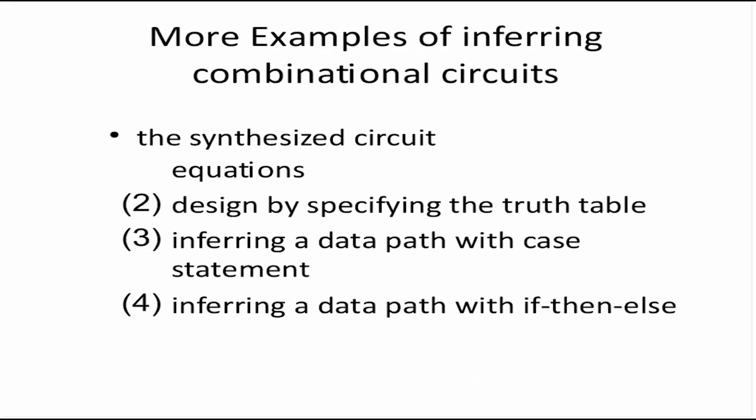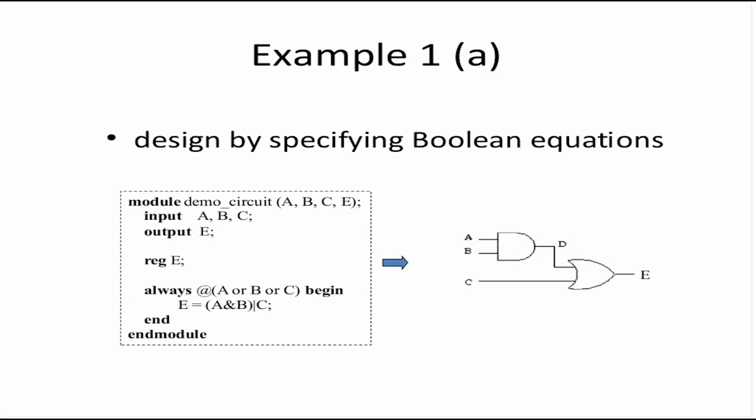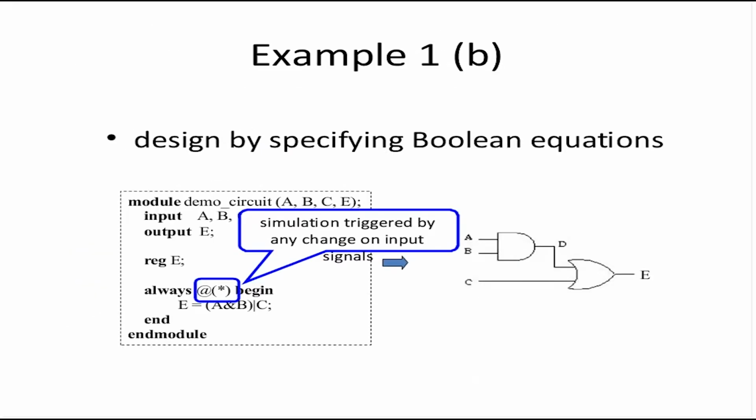That is why a very good practice is to use always @(*). It tells that simulation will get triggered by any input, and DC will synthesize it correctly, and you will never have a simulation-synthesis mismatch. So this is a very popular coding technique, always @(*).